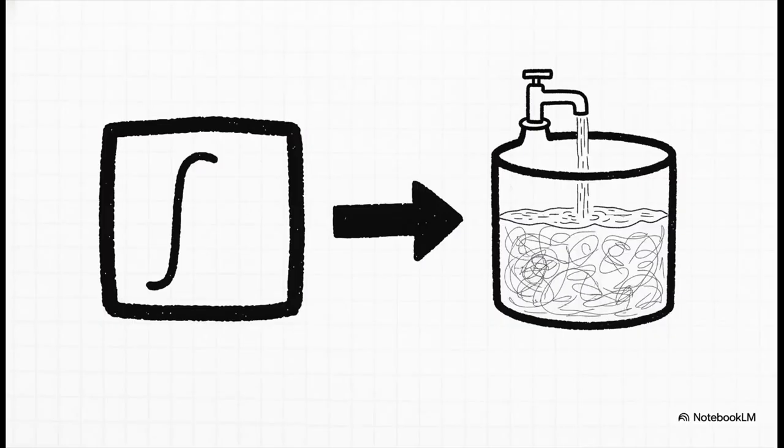There is a really critical detail when you're building this out visually, though. You have to use the integrator block for the capacitor. Why? Because the voltage across a capacitor is inherently the mathematical integral of the current flowing into it over time. If you accidentally used a differentiator block, it would be mathematically wrong. The integrator perfectly models that physical accumulation, just like water filling up our tank.